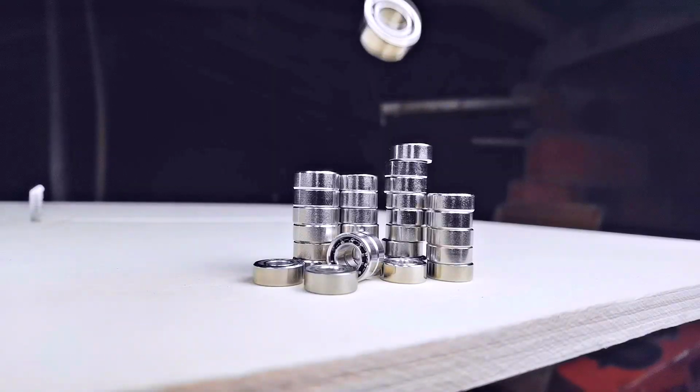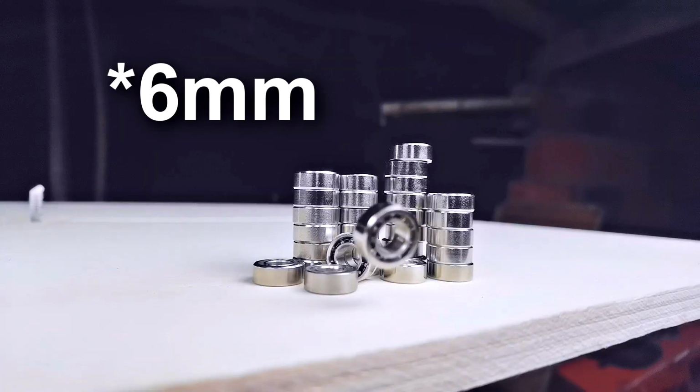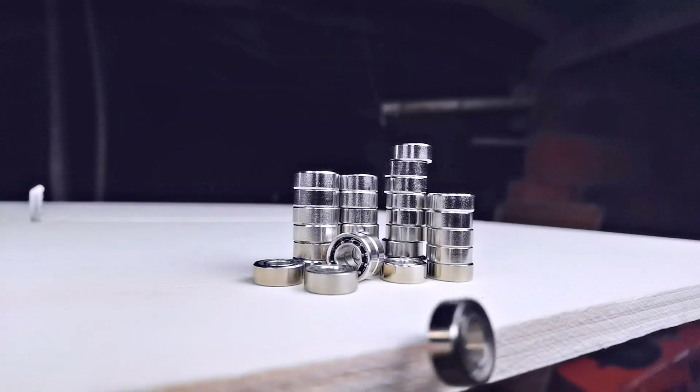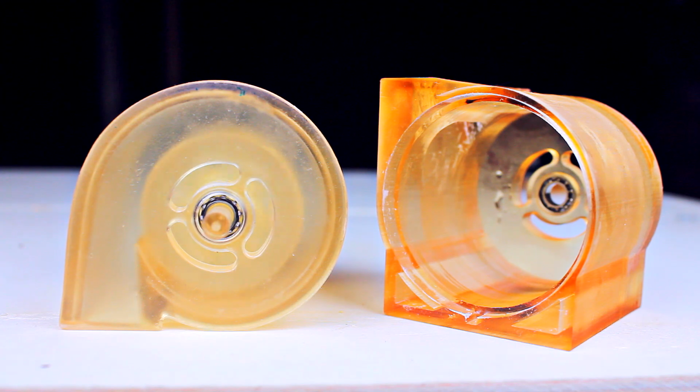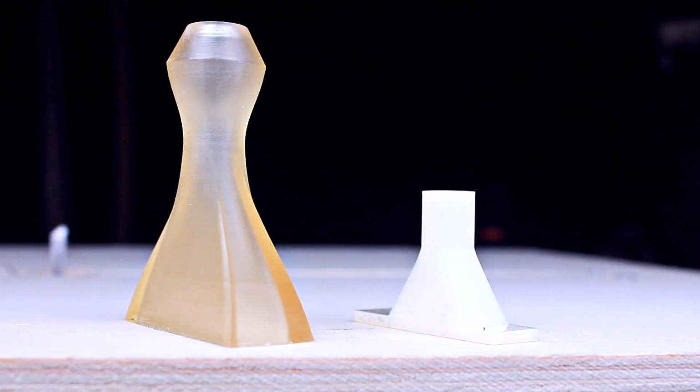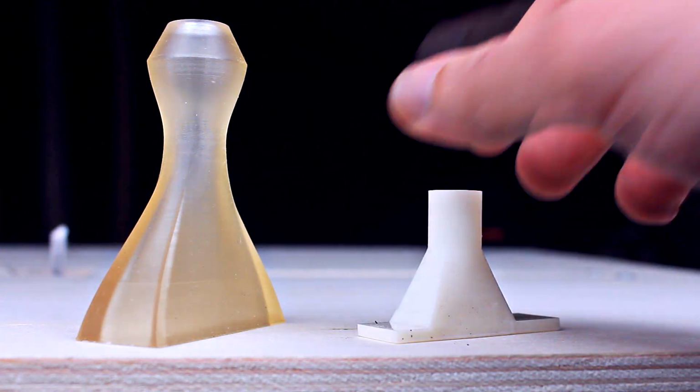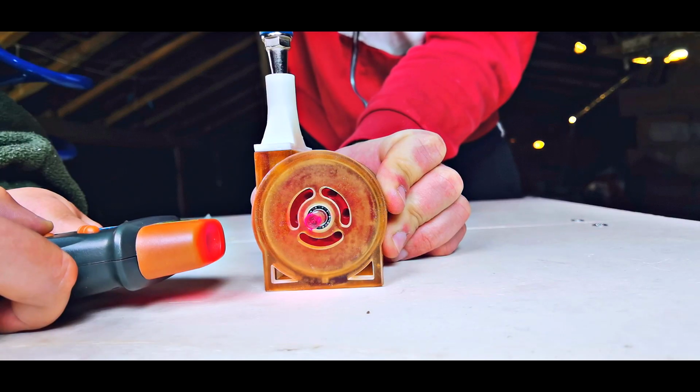As supports for the axis, I used 60mm ball bearings, which are capable of reaching insanely high speeds. I printed out both casings and the respective lids, and also one convergent-divergent nozzle and one standard nozzle. I assembled everything, and I used my compressor to make the speed test.